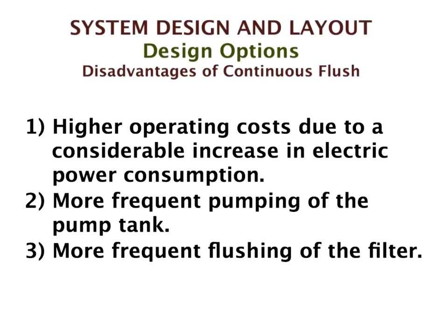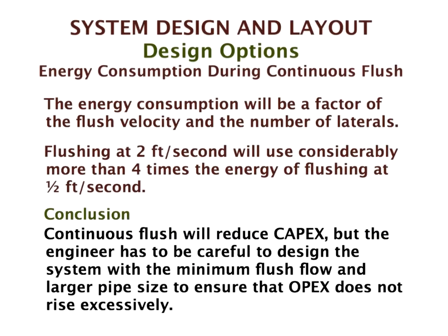And your filter is going to have a greater load, so there might be more frequent flushing of the filter. None of these things cost a lot, but when you add them up, they might be more than the capital cost saving that you've got away with to sell it to the homeowner that you've got a lower price.